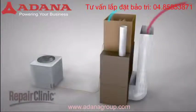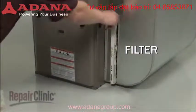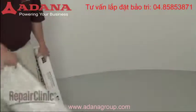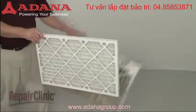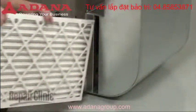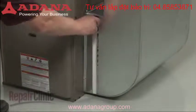The most important factor in efficient operation is airflow. To ensure proper airflow, the air filter should be checked monthly and replaced as needed. There are several types of filters available and range from 1 to 5 inches thick. The filter can be installed into the slot in the return or in an air cleaner.